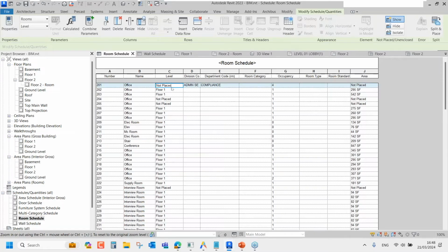For example, in a Revit model, Revit will tell you if there are spaces that used to exist that no longer exist in the model, and that might be a duplicate, for example. So that's quite easy to see. That'll tell you if that has been removed from the model, and that might help you clean up your Archibus data at the same time. So having these schedules is a nice feature for a facility information model.